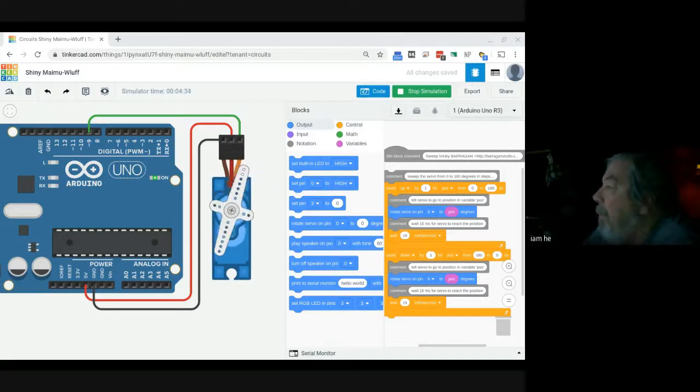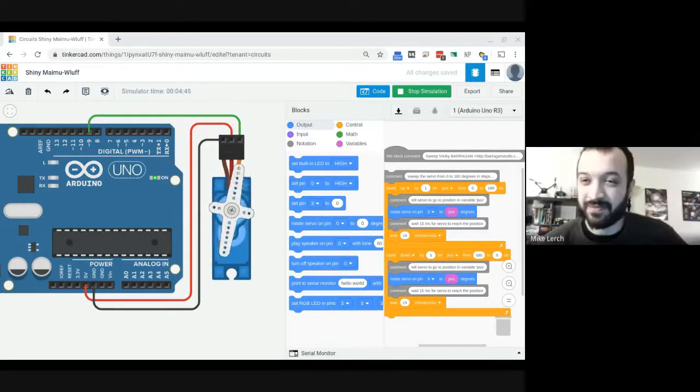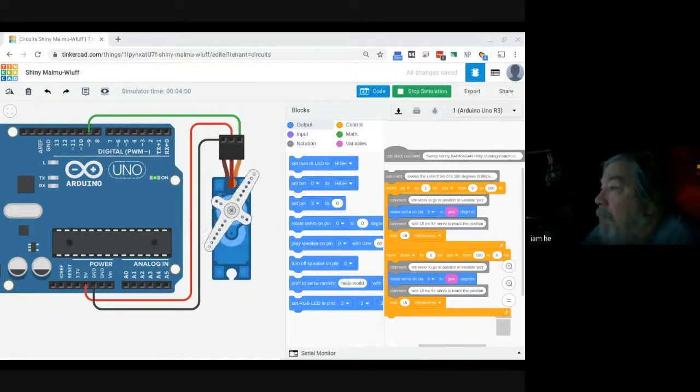The little project I'm working on with the microbit uses 4 of these guys, but the load is light because all it's going to do is be like an arm or a leg that's moving, and it won't move that much. That's 180 degrees it's turning. So I will only have it move like 20 or 40 degrees, just a little bit. And so I don't think a piece of cardboard weight is going to be much of a load on it. But I can't run 4 of them on the microbit. I have to run it through a separate set of drivers. It gets a little tricky to do, but nonetheless, we're on the right path, I can tell.